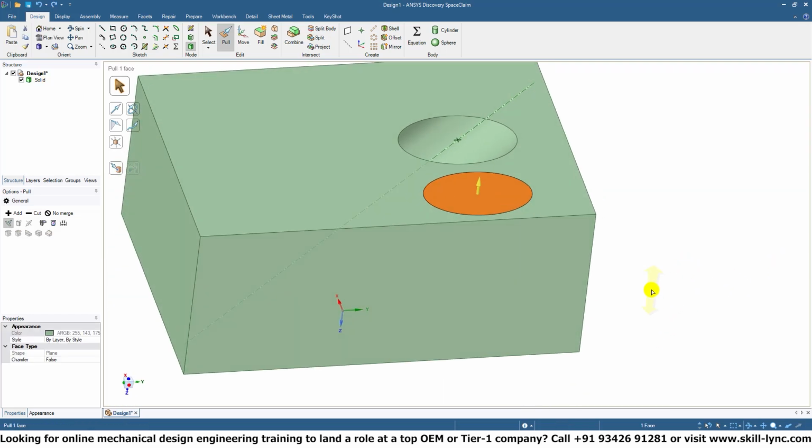And you might think, oh, how would I actually do that? How would I be able to recreate this hole without creating a normal circular hole and then moving it, because you wouldn't be able to give precise dimensions when you use the move tool? There is an actual way that you can do this. When you select the pull tool with the cut feature, one of these buttons, the same button where you click sweep and the same button you click to get a revolve or scale, you can actually select the pull direction.